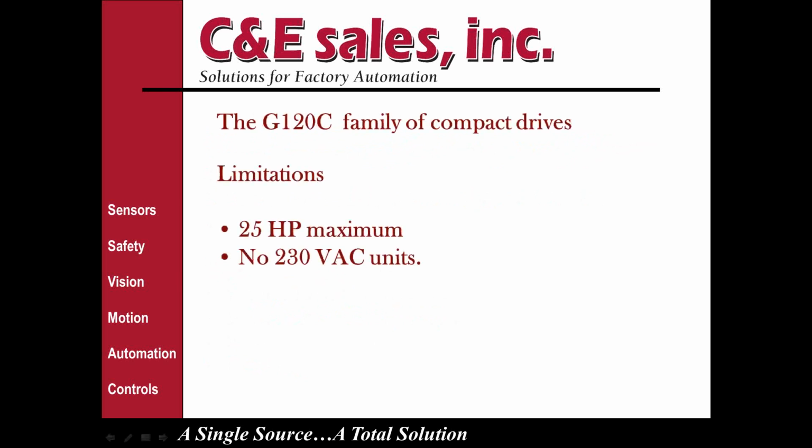Limitations are the 25 horsepower maximum and it's only available in the 380 to 480 volt range. There are no 230 volt units.